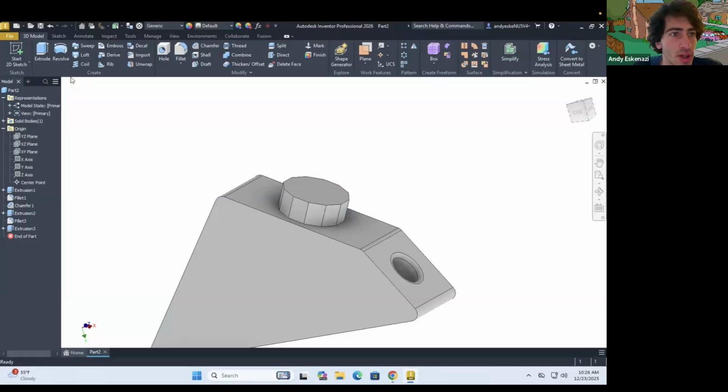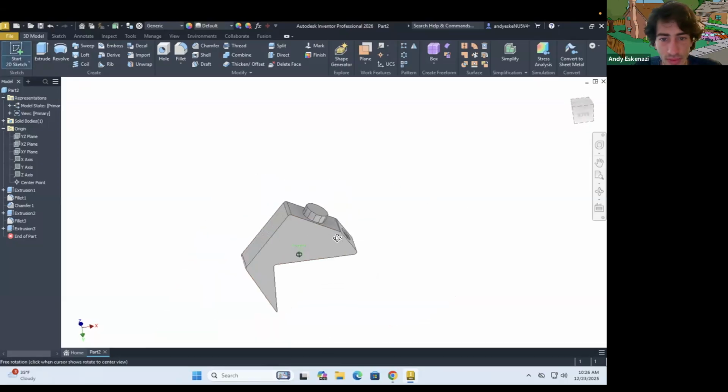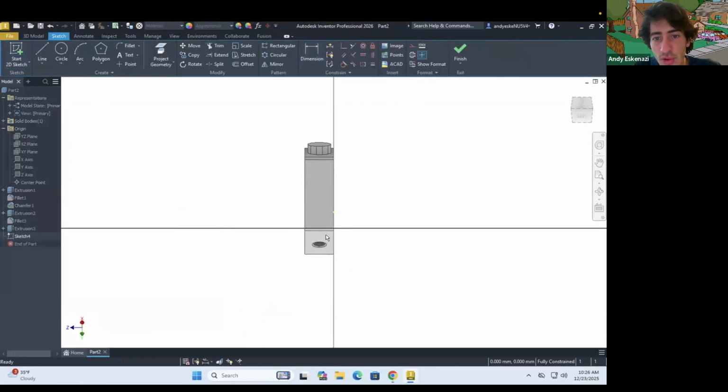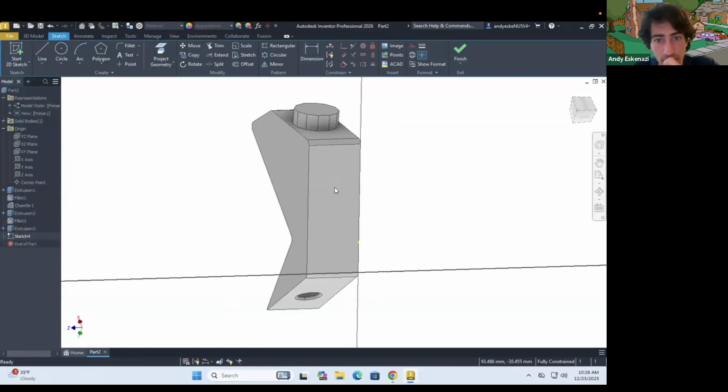What else can we do from here? Let's do another sketch all the way there. Suppose now that I wanted to do another slotted cut that goes through this piece. So here to line, I'm gonna make a reference line. That's why I click in there. I'm gonna click on a point, boom, another point, all the way like that. So it's 3 lines. I'm gonna make this line control that line equal. There we go. And then I'm gonna click on D. I'm gonna make that 50.